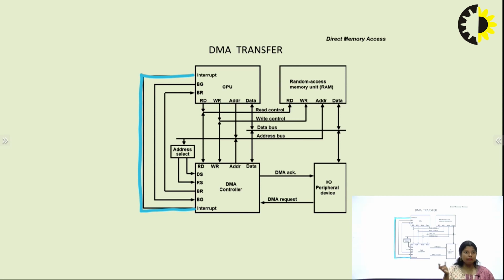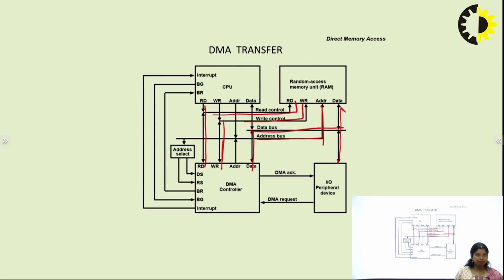Interrupt, as we already discussed: if the DMA controller has an enabled value, the other devices can interrupt. Otherwise, if the interrupt value is disabled, at that moment other IO devices cannot interrupt during that particular transmission.